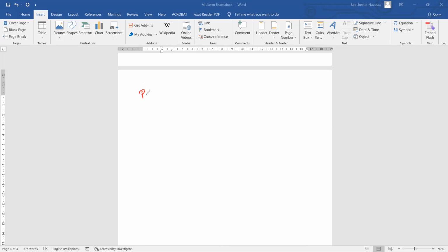Your P sub U comes from the two load combinations. So straightforward, ang governing load combination dyan is 1.4 dead load plus 1.7 live load. So therefore, your PU is 1,400 kilonewton. And your MU, sino lang ba dito yung may earthquake loads?